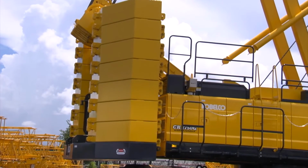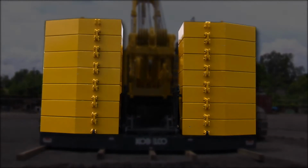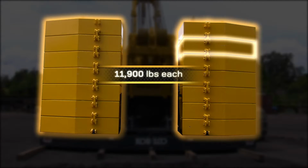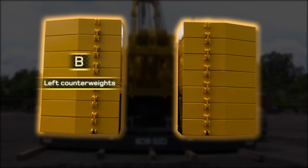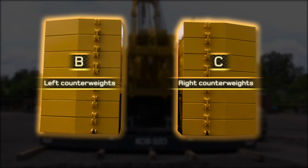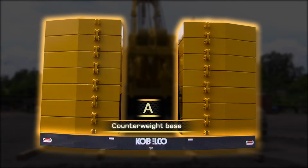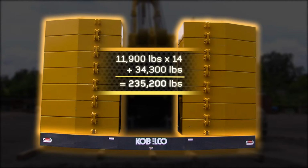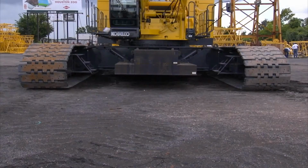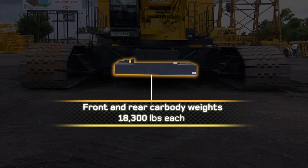On the back of the upper portion of the machine is the rear counterweight assembly. This assembly has 14 counterweight pieces, each weighing 11,900 pounds. The weights are stacked in 2 stacks of 7, referred to as B, your left counterweights, and C, your right counterweights. These counterweights are placed on a counterweight base, which is referred to as the A counterweight, weighing 34,300 pounds. When all 15 pieces are combined, the total upper counterweights are 235,200 pounds.